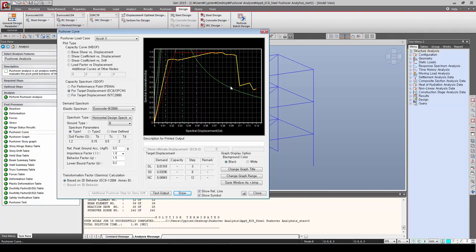For the detailed formula of the target displacement, refer to Annex B, determination of the target displacement for nonlinear static pushover analysis. The target displacement obtained from the above corresponds to the seismic demands of the limit state of significant damage. Target displacement of the limit state of near collapse is taken equal to that of the SD multiplied by 1.5. Target displacement of the limit state of damage limitation is taken equal to that of SD divided by 2.5.